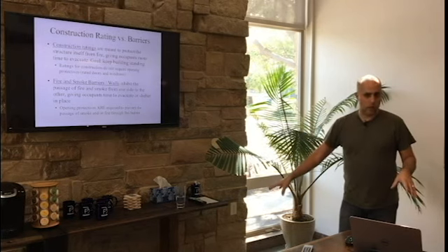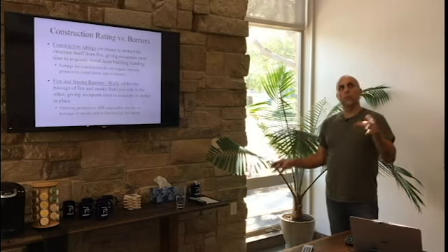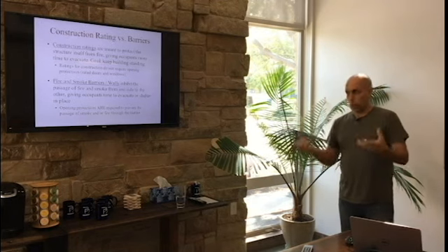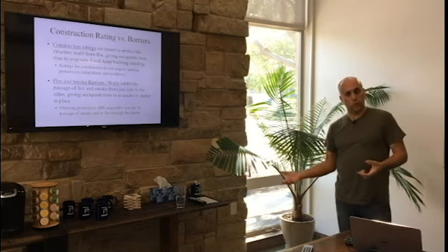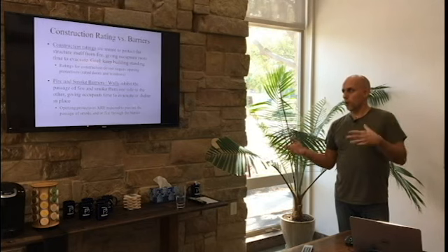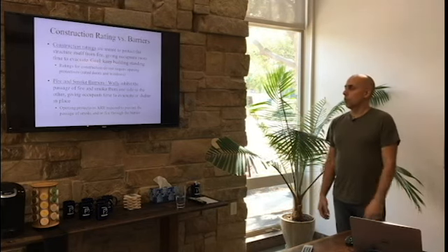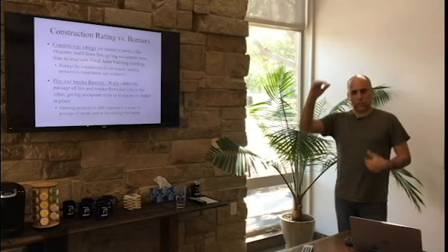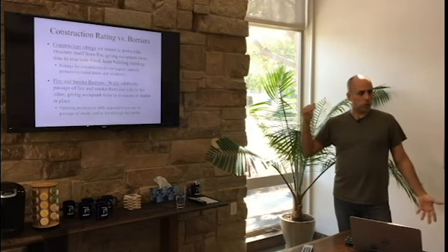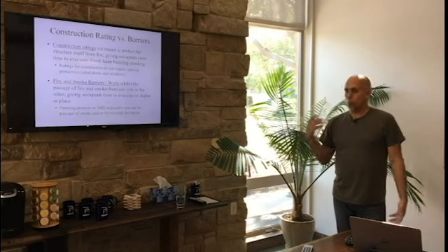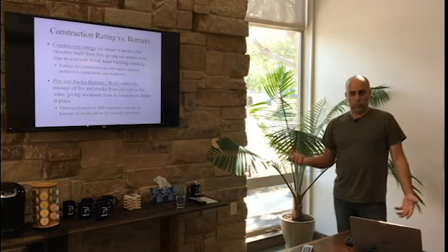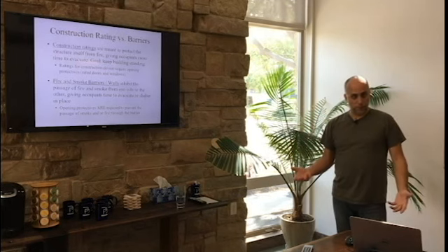There really isn't a 3 hour in terms of total time for the building. There are some building types that require 3 hour components, but they generally are because the other components of the building are less than 3. So most of the ones we do are 1 hour because we typically stay below a certain number of stories. But the whole point is you can't get out of a building if it's falling down around you.